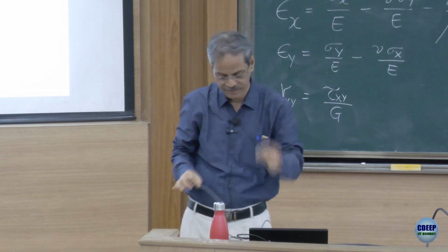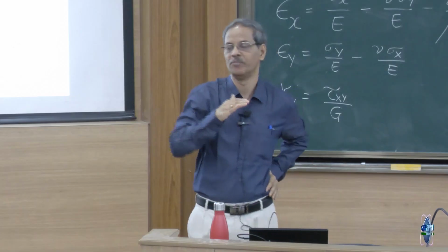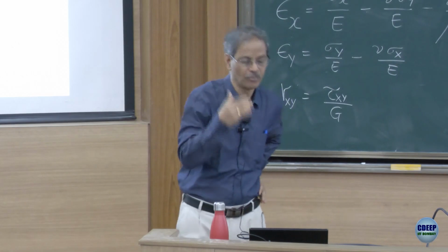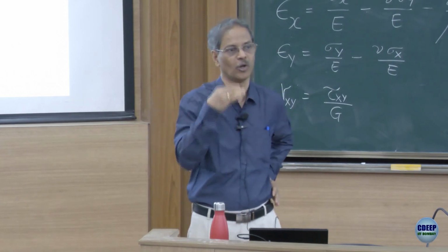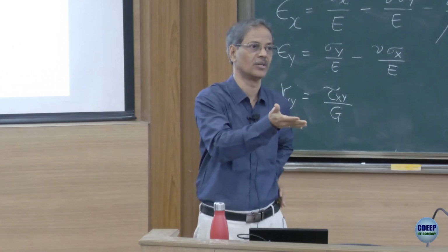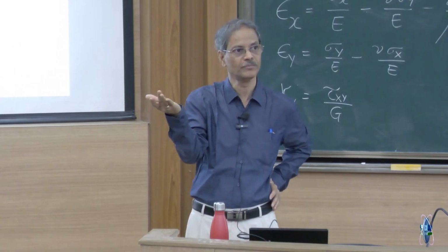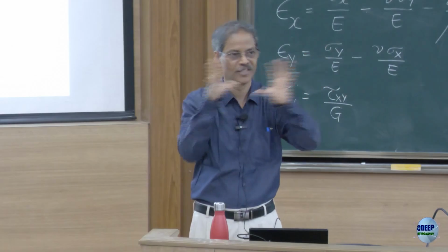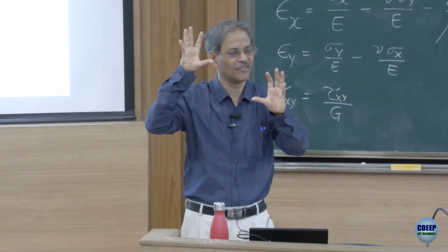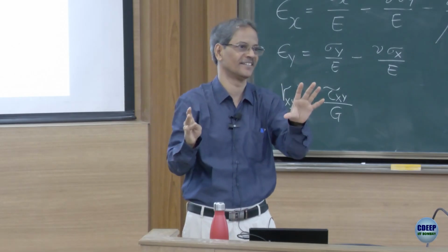So I would want you to think in terms of these natural coordinates, and when we meet again after the mid semester, I would be discussing from this point of view of formulating the natural coordinates for quadrilateral elements, that is rectangular domains or triangular domains, and then do all these computations back and forth, etc. xy is where the physical action is, but all the mathematical action happens in zeta eta.